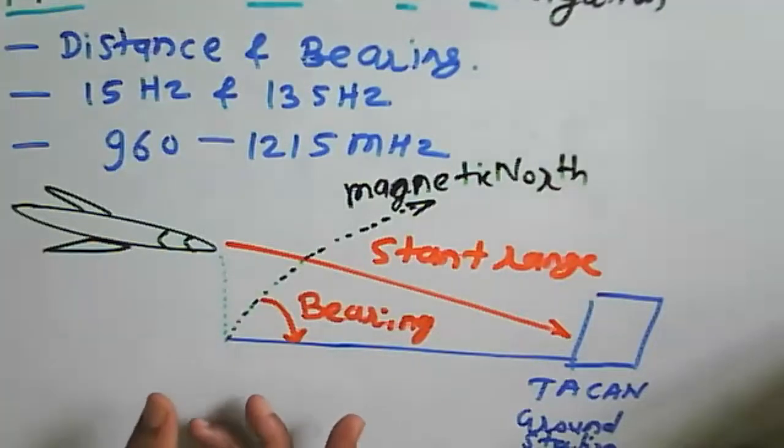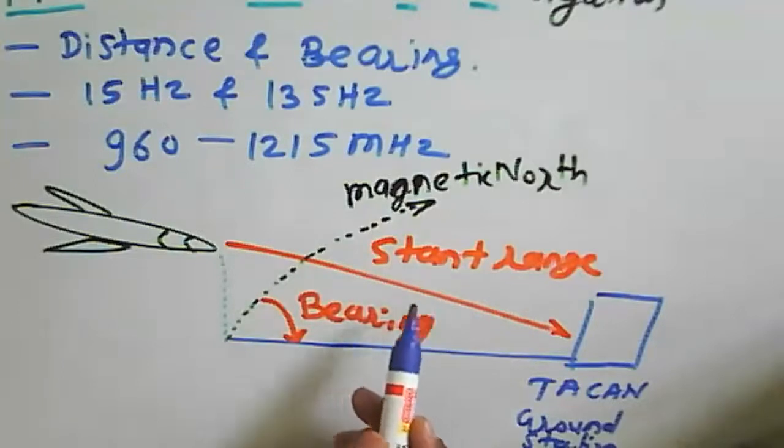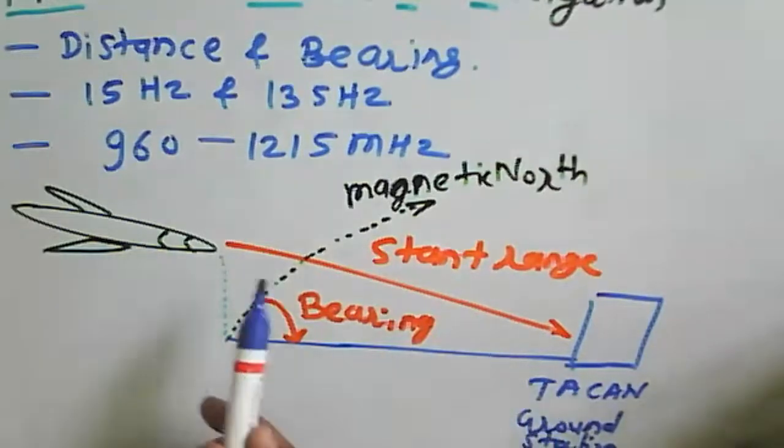Similarly here, it determines the round trip travel time of the pulsed RF signal, and whatever echo signals are received there, according to that it will find out the range. Mostly it is like considering the signal to be transmitted, and then how much time is taken by this particular signal. That signal travel time is useful to determine the round trip travel time, and that will be useful to determine the range of the aircraft. Okay, so we can say that is the distance here.